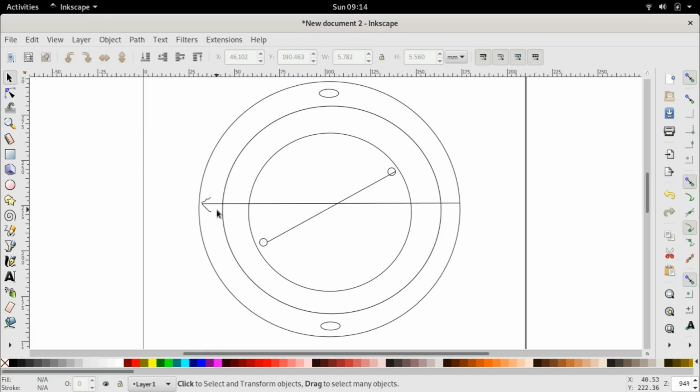It will be 0, it will reach a maximum, it will go back to 0, and then it will reverse direction. It will be from the left to the right. It will again go to a negative maximum, where again it is from the left to the right, but it has now maximum strength, and it will go back to 0, and so on and so forth. Right? So this stator flux is an AC flux which follows the same pattern as the AC current.